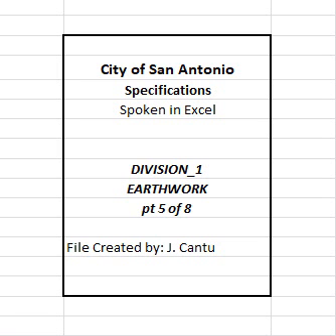A. Earth embankments. Earth embankment is mainly composed of material other than rock. Construct embankments in successive layers, evenly distributing materials in length suited for sprinkling and rolling. Obtain approval to incorporate rock and broken concrete produced by the construction project in the lower layers of the embankment. When the size of approved rock or broken concrete exceeds the layer thickness requirements in section 107(3)d, compaction methods, place the rock and concrete outside the limits of the completed roadbed.